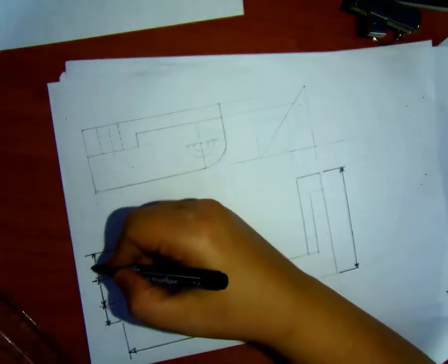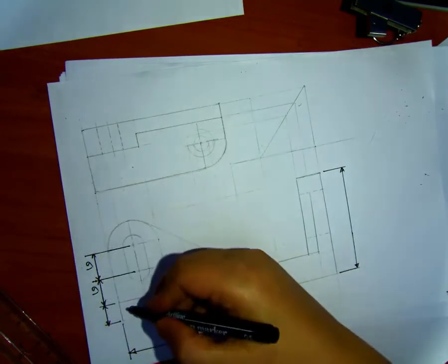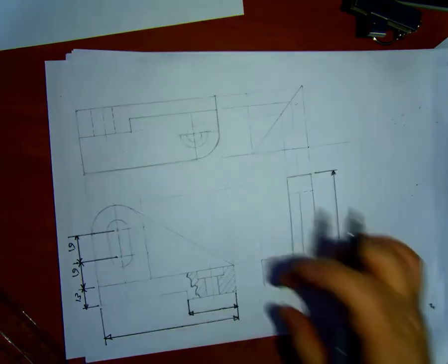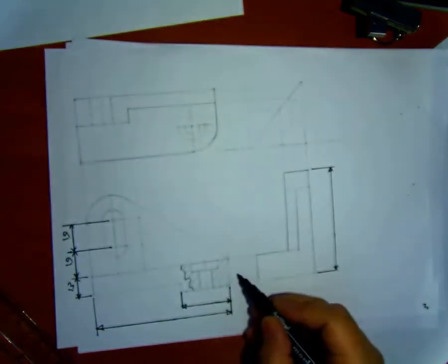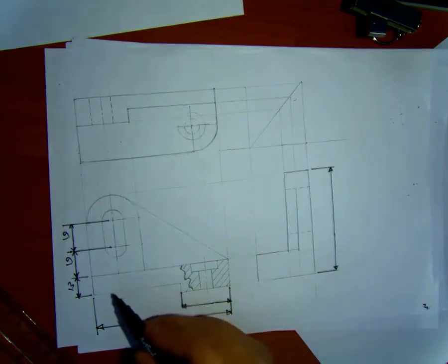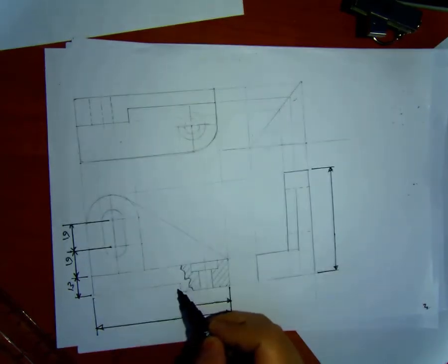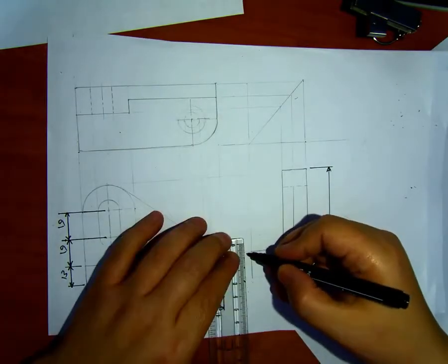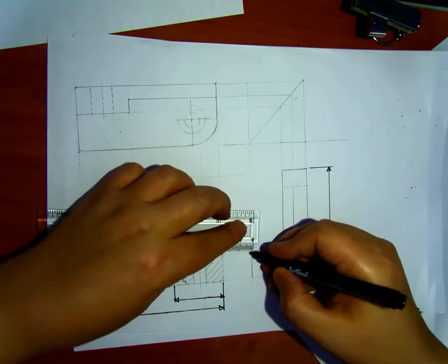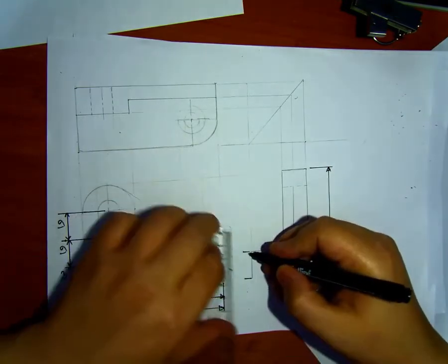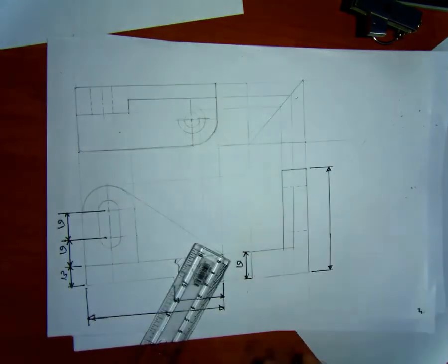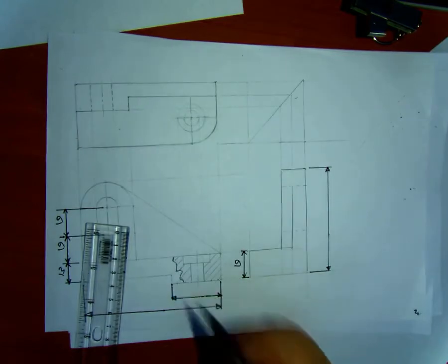Okay, and then we will draw as an example 19, and this value was 13. Okay, if you draw from here to here 19, then you don't need to draw this value from here to down, or this value 6. Okay, because this will be an extra, repeated dimension. So let's say I want to add this dimension to this view here. Okay, 19. So I don't need to add here 19 or here 6.